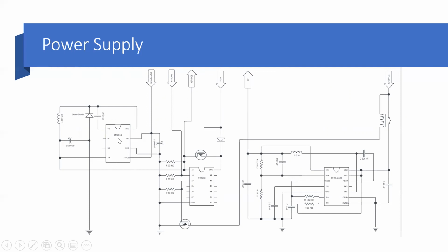And this voltage regulator is for the vehicle accessory, so we can know when the car is turned on and when the car is turned off. So this provides like a latching mechanism so that when the car is turned off, the Raspberry Pi Pico will sense that the car's been turned off. We'll be able to keep the power supply on long enough to write to the SD card the current draw values that are being measured. And then the Raspberry Pi Pico can then turn off safely the power supply.